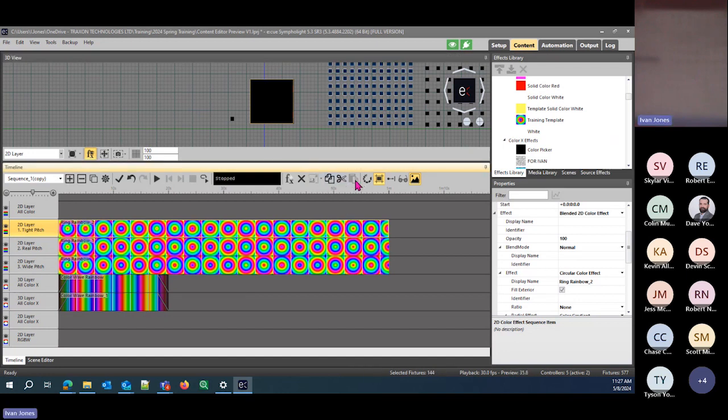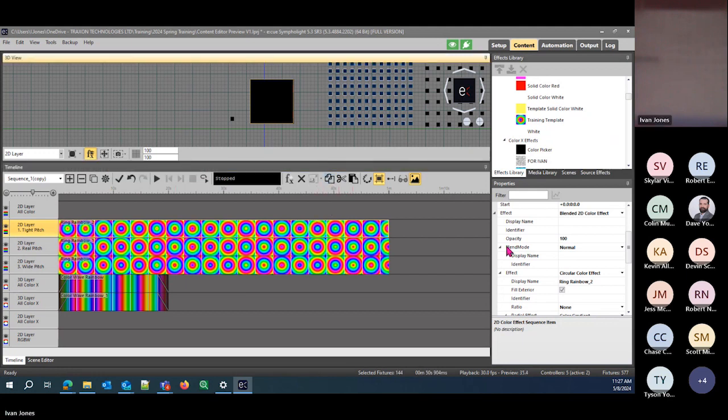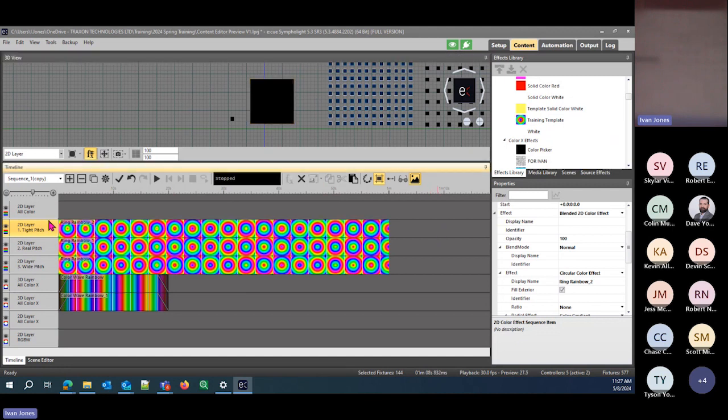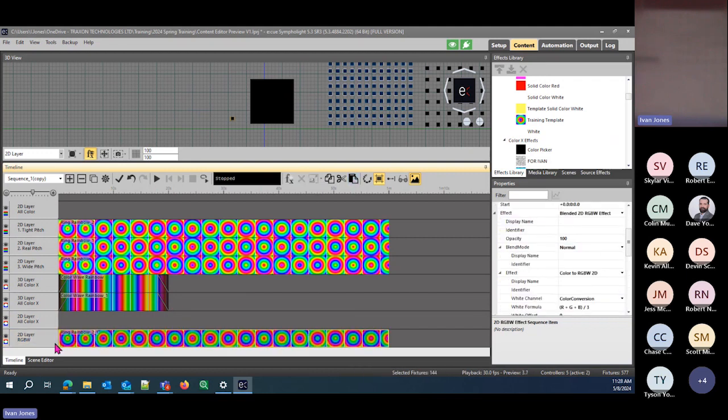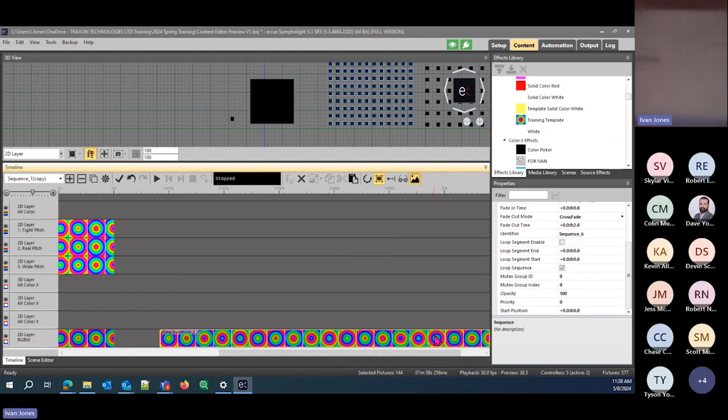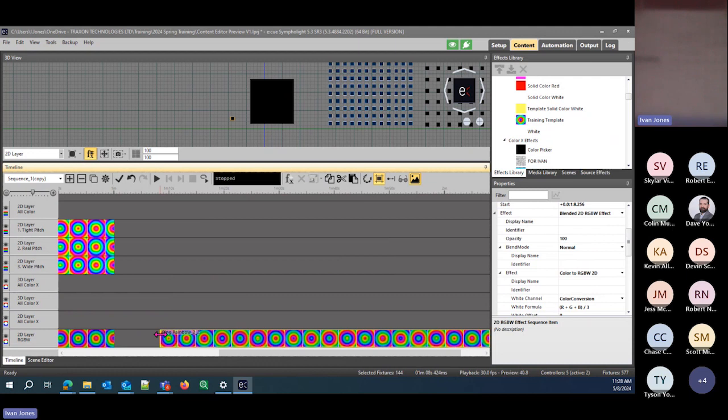We have copy, cut, and paste here. So when I copy an effect, I can choose to paste it, and I will select which track it's going to paste into, hit paste, and it will go in at the space that's closest to 0 seconds. So if you want to make sure there's no gaps, you always do that. Otherwise, if I use Control V on my keyboard, it will paste where that mouse cursor was.